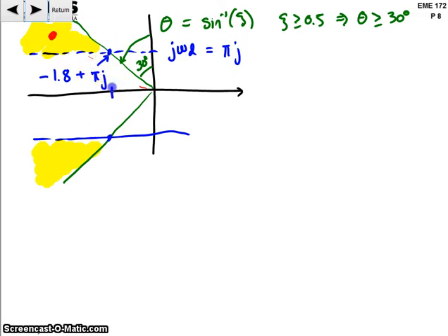So this line here, sort of where these guys are at, it's at minus 1.8. Okay, and pi j, obviously that's from the peak time specification. I calculated that because I drew this 30-degree line and I found where it intersected that dashed blue line.